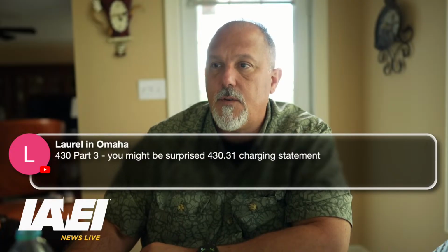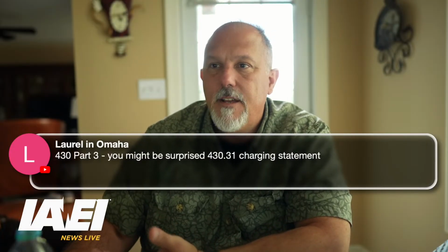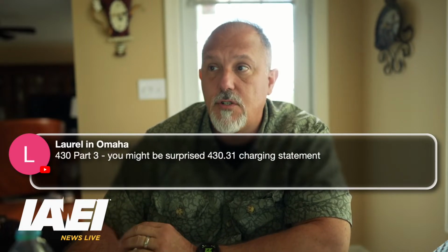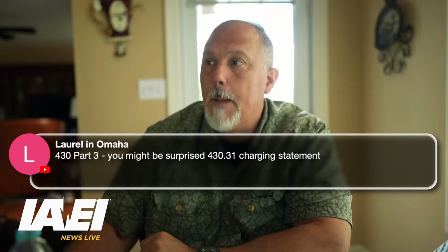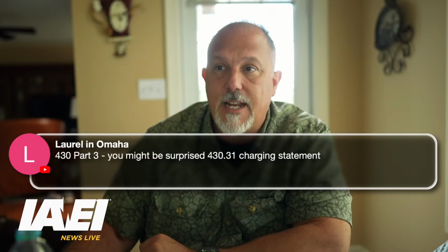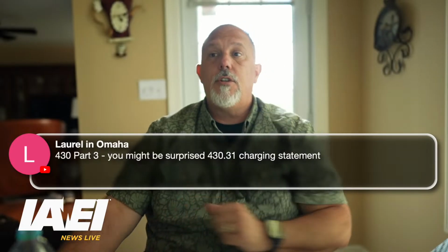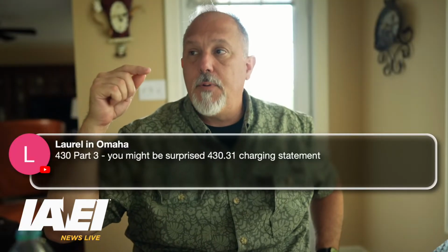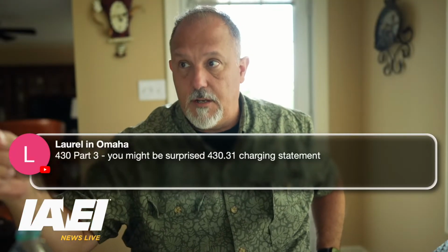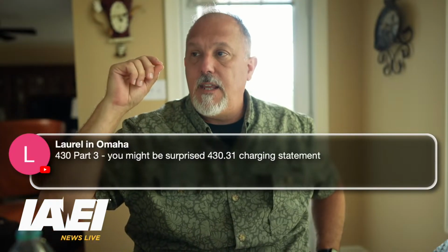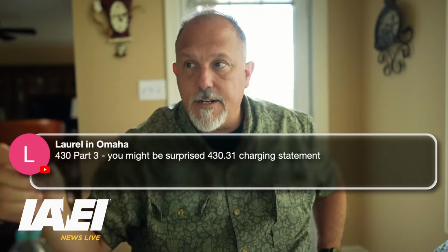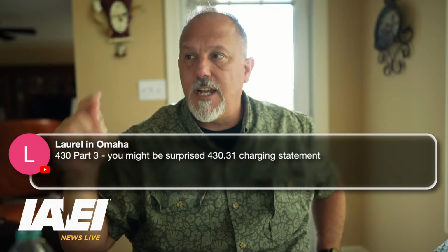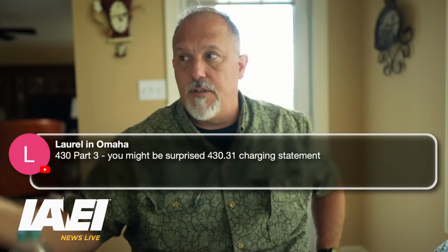The secondary circuits of wound rotor AC motors, including conductors, controllers, resistors, and so forth, shall be permitted to be protected against overload by the motor overload device. So that tells you, in my mind, they're giving you a specific permission that the conductors, controllers, resistors, etc., are permitted to be protected against overload by the motor overload device.